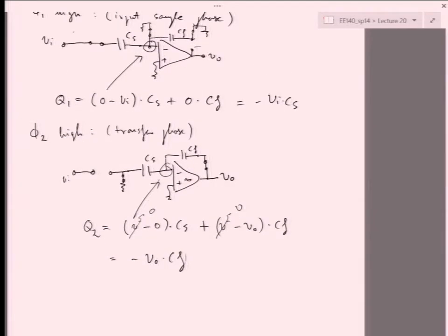Notice because we didn't have the overlap between the switches, in both of these cases, the charge actually remains the same on Q1 versus Q2 on this input node to the amplifier. Also because in CMOS, this input amplifier's current is 0, right? It's just hitting the gate. In bipolars, it would be hard to do this. You'd have to sort of account for some discharge of that node due to the base current, right?